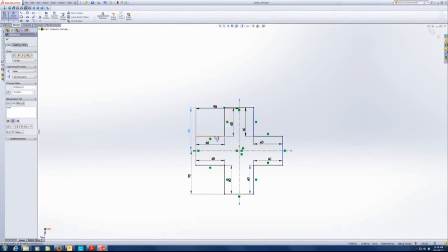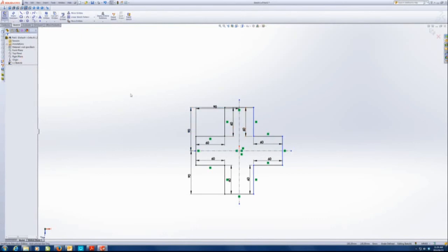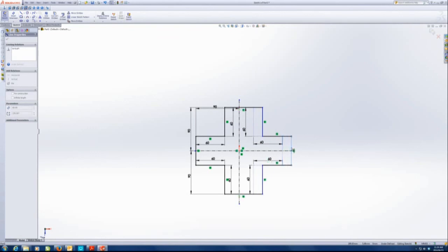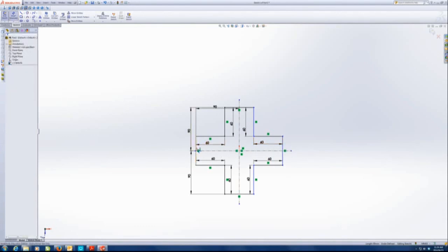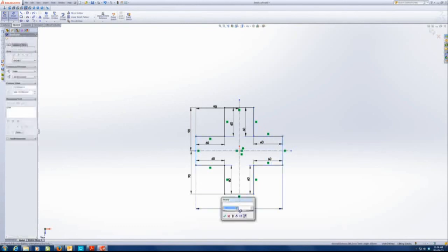Now that line and this line are both blue. Now pick another line, and please, you need to not have any tool selected when you do this, otherwise you're going to draw an extra line or something like this. Now we come here, click on this line, we drag it, and it's moving in the X direction. So we need to constrain it from there to there, or from there to there, either way. As long as we constrain it in the X direction. So we're going to go from there to there, and that is 180. Okay, and there we go.